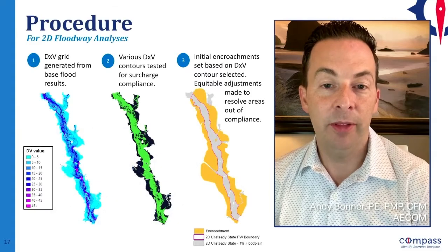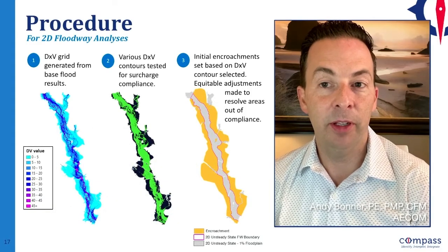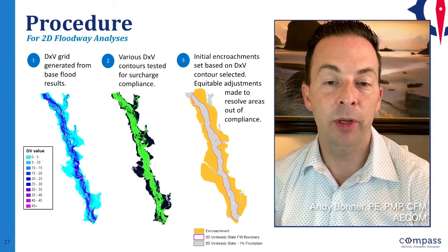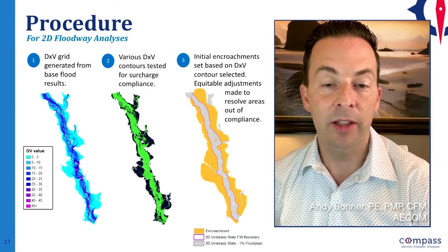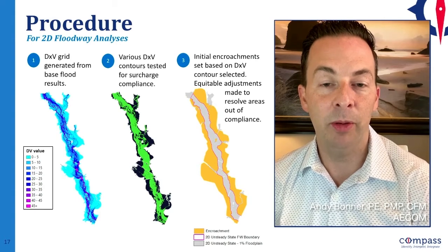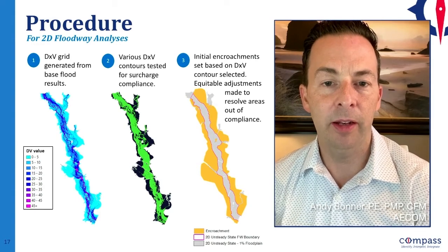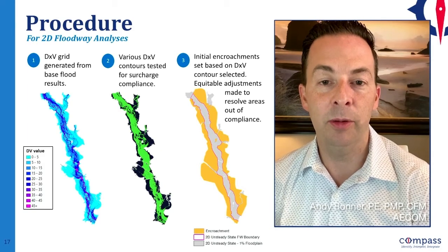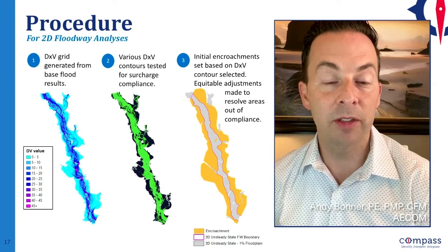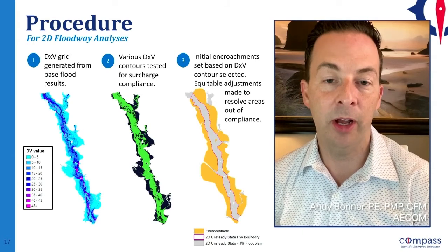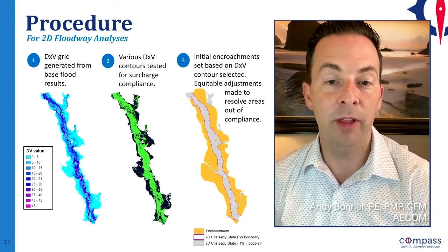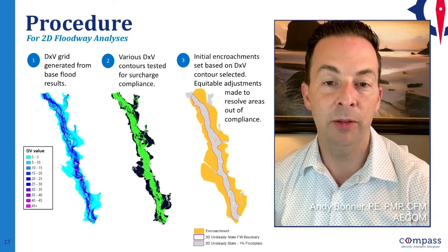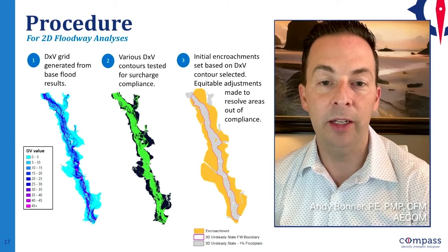So in 2020, the guidance and standards were updated related to floodways. One of the adjustments in one of the standards was to replace the equal conveyance requirement with something a little broader that would apply to both 1D and 2D. So there was this reference to equitable consideration of both overbanks, hydraulically speaking at least. And the way to do that, outlined in the guidance, was to leverage the depth and velocity data from the 1% annual chance unencroached floodplain for that purpose.